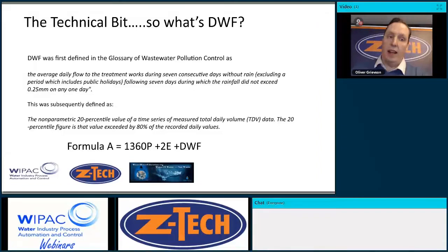DWF, I'll come on to a bit later, but when you go into the history of DWF, again, it's not the easiest thing to understand, which you can understand why people have said, oh, Formula A, 6 times dry weather flow. A lot of the smaller wastewater treatment works out there, a lot of the treat all flows works, are designed to 6 dry weather flow.